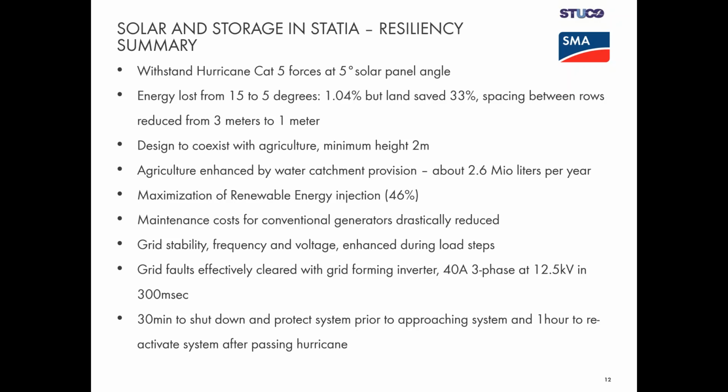Grid stability, frequency and voltage are enhanced, not only in diesel off mode, but continually, because the solar park continually functions as a backup. So the grid stability, frequency, and voltage are kept in margins that heretofore were impossible with our conventional gensets.